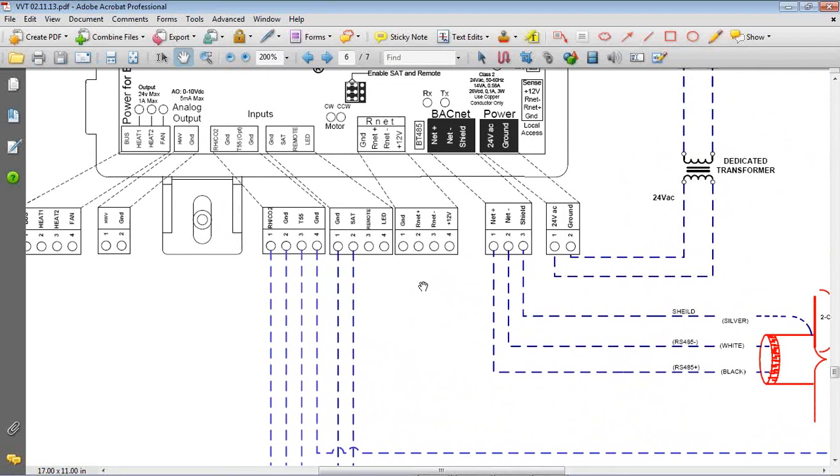The next plug would be an RNet sensor, which is one of the different space temperature options that you can use with these controllers, and I'll show you those in a minute here. But it is a 4-wire connection, and the good part about these sensors is that there's a plug input in the bottom of them where you can plug in the Field Assistant servicing software, and you can access the entire system to do programming.